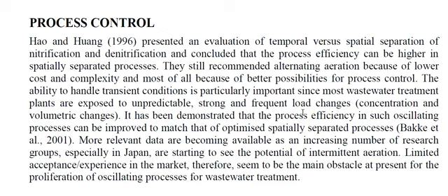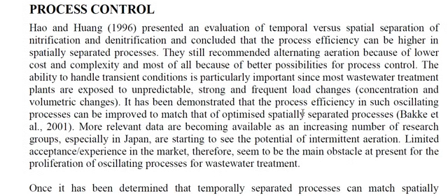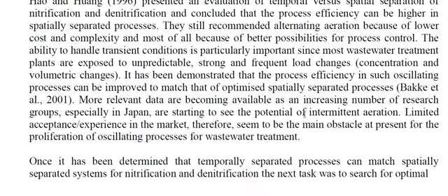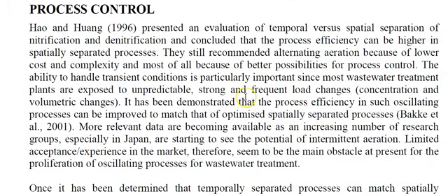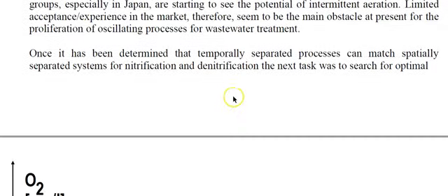Now then, if we go back to the high-tech part, the process control, we have in these cases tried to achieve nitrification and denitrification in one chamber. Like we tried when you were doing your modeling for nitrification, we had this aeration on-off. Well, we used that in these small plants, so that way we achieved nitrification. And there are also some references to people who have published this kind of work.